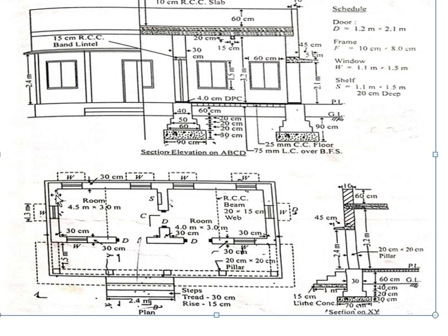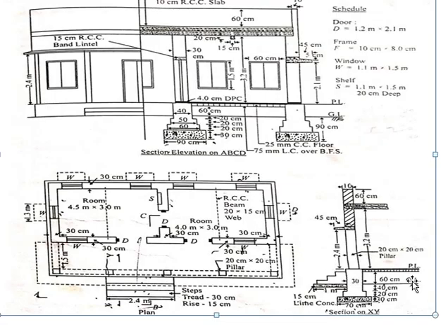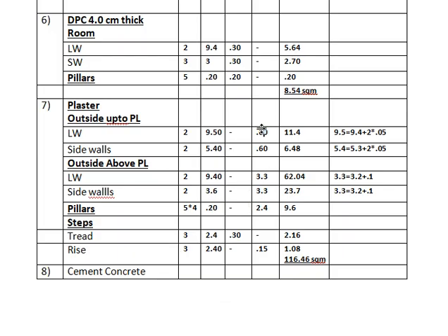You can add 0.3 plus 4.5 plus 0.3 plus this 4 meter plus 0.3, this is the length, and that turns out to be 9.4, and you have to add the offset of 0.05 meter on both the sides, which will make the total length 9.5. Now talking about the height from the ground level up to the plinth, it is given here. You can see from ground level to the plinth it is 0.60 outside, therefore it's 0.60 here. Similarly for side walls, we have two side walls.